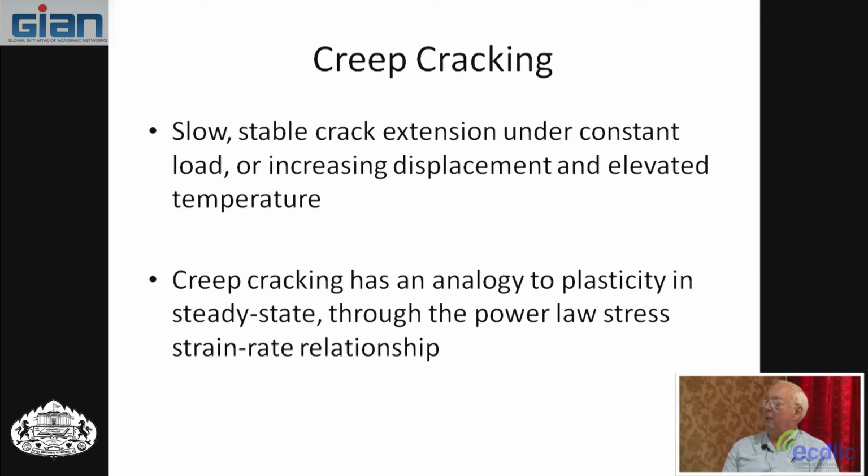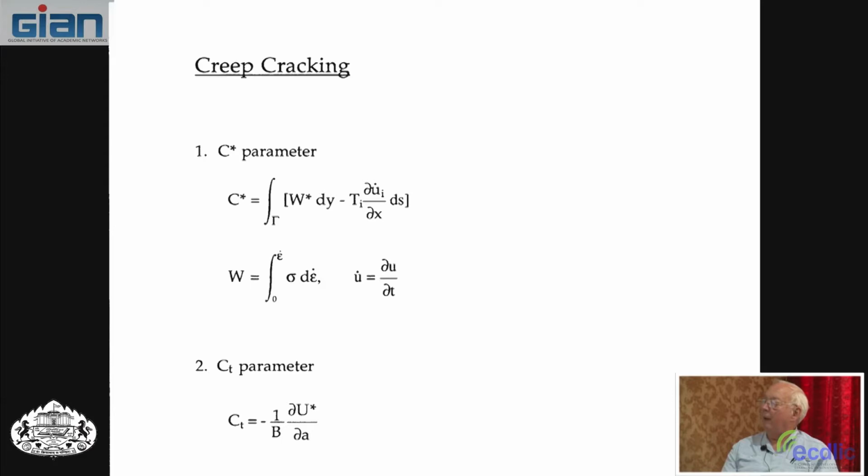We said if you get above the threshold, then you would normally have failure in a short time, usually hours or days at the most. Creep cracking has an analogy to plasticity because of the power law relationship in steady state region 2. So that was a help in creep cracking.